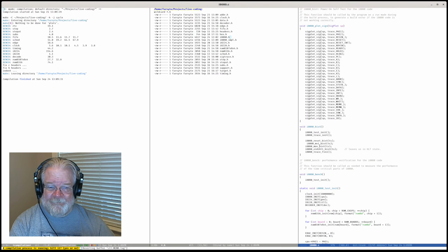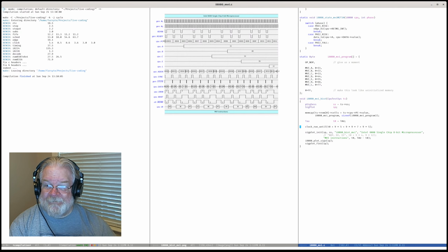So 3E, FF, 22, 0E, FF, 44, 1E, 1F. This is stuff going into IR. So 3E is the instruction. We're getting another instruction of FF. What are we fetching here? PC is 3, 4, 5, 6, 7, 8, 9, A, B, C, D, E, and so on. That's correct. 2, 3, 4, 5, 6, 7, 8, 9, A, B, C, D.